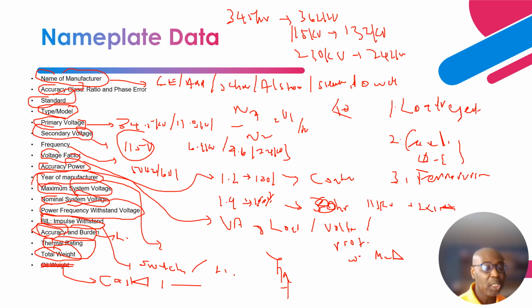Oil comes into play when you have voltages above 34.5 kV, or maybe around 34.5 kV and above, when you have to utilize high voltage inductive transformers, where the winding is immersed in oil. But in medium voltage applications, most often it's cast resin or epoxy resin.